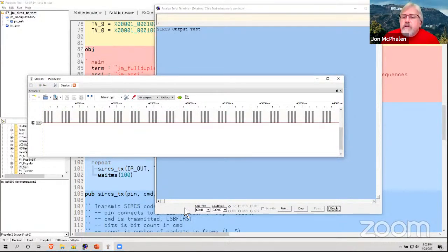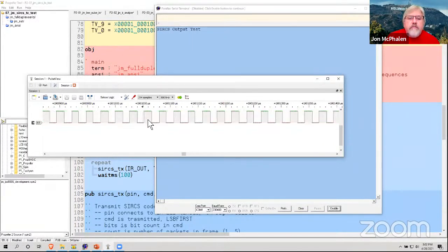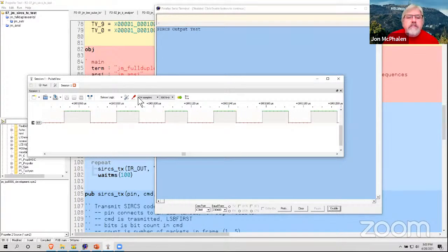So can you see on the screen those packets of 3 pulses? And remember, I selected TV 8, so it was the 8 button, and we have to take the button number and subtract 1 from it. So here's 7. So here's a start bit. Here's 1 1 1 0 0 0 0. So there's the code for 8, and then here's 1 0 0 0 0. That's the TV remote.